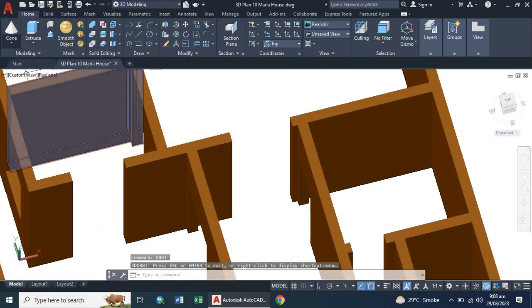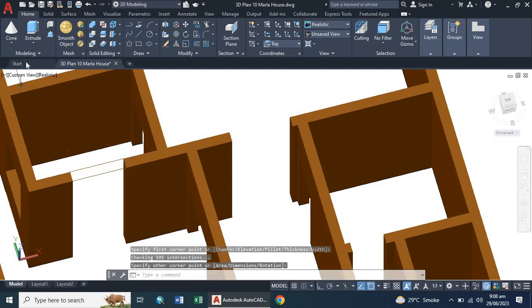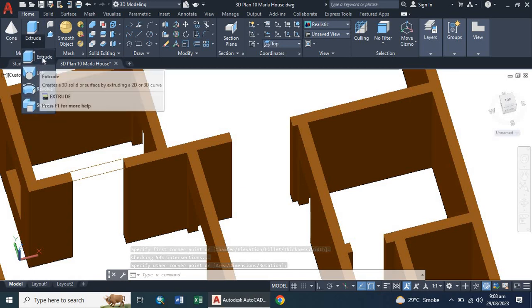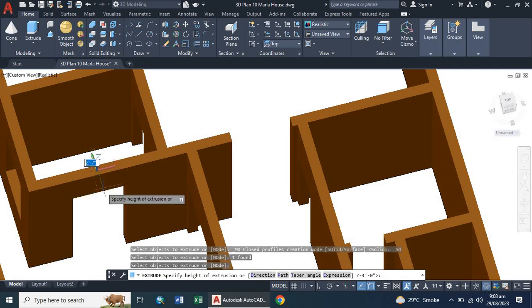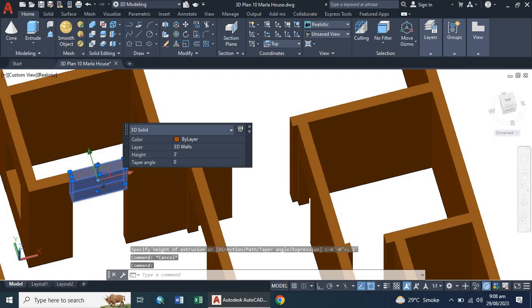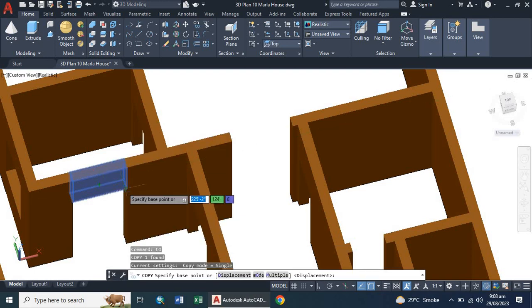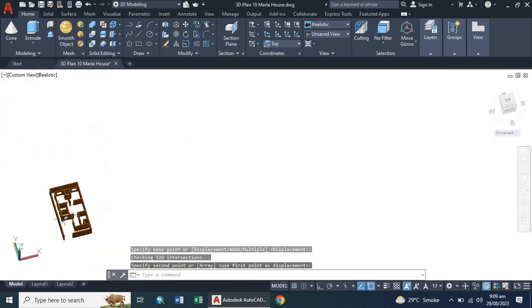So first of all, we have to provide a sill level and level above lintel for the kitchen for window placing, and after that we will go with our doors, pressing enter 3 feet at the upper side, and select this one and copy this thing from the bottom point and it will be here. So this is actually a space for our window.